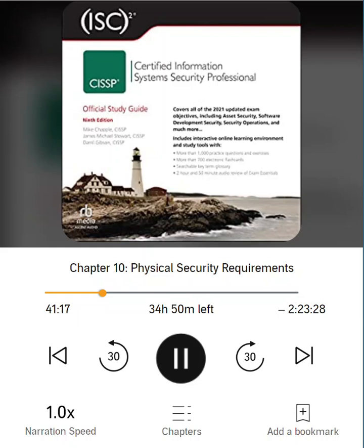Thus, a reliable detection and alarm system incorporates a heartbeat sensor for line supervision. A heartbeat sensor is a mechanism by which the communication pathway is either constantly or periodically checked with a test signal. If the receiving station detects a failed heartbeat signal, such as the loss of the constant signal or missing one or two interval checks, the alarm triggers automatically. Both measures are designed to prevent intruders from circumventing the detection and alarm system by cutting power, cutting communication cables, or jamming radio signals.